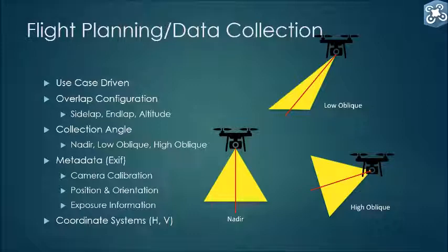What is important too is that the drone collects certain types of metadata. At the very minimum, the X and Y, latitude, longitude, and altitude values. The addition of orientation, focal length, and pixel size of the sensor will also greatly improve your results. So get to know your drone, get to know its abilities, and ensure that in your flight planning, you set what needs to be there to capture the quality of imagery that you need. There are many commercially available drones, and they have at minimum the ability to capture latitude, longitude, and height, but depending on your own needs, what you get might vary.